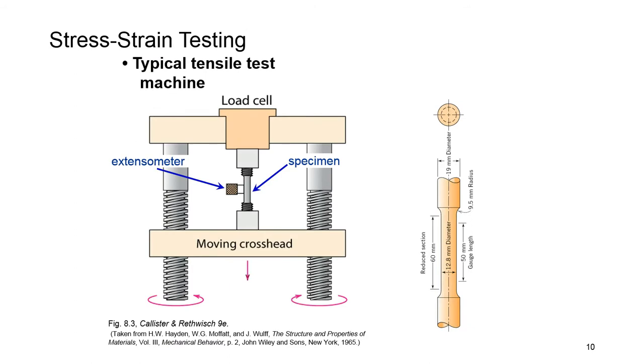To find tensile and compression properties, the stress strain curve of a material, a tensile test machine is used. This is a typical tensile test. As you can see, the specimen is inserted here, and then this screw is rotating, and what's happening, this head is fixed, and by this screw going from the top view clockwise, the crosshead is going downwards. Therefore we have tensile load applied on this bar, and then it results in tensile stress. The displacement can be measured using this extensometer as shown.